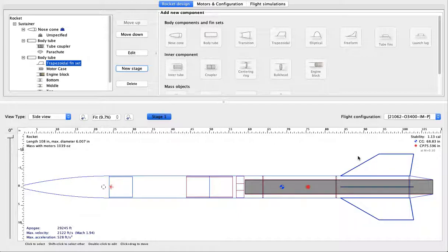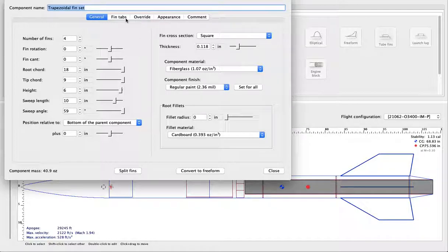Now, I said I forgot something about our fins. Here, our fins, of course we glue them to the body tube, and we'll do certain processes to distribute the weight along the body tube. But the best thing about having a motor that's not minimum diameter, meaning the motor doesn't take up the entire outer body, is we can actually attach our fins directly to the motor tube, which means the real root of them is not on the outside, it's on the inside, and those things aren't coming off at all. And so we can do that manually.